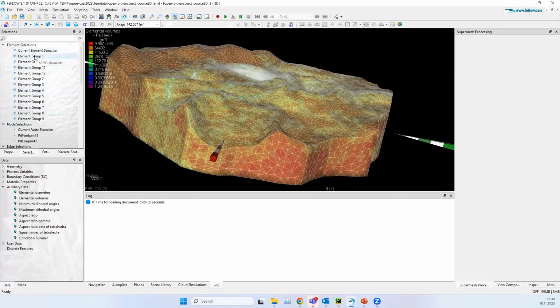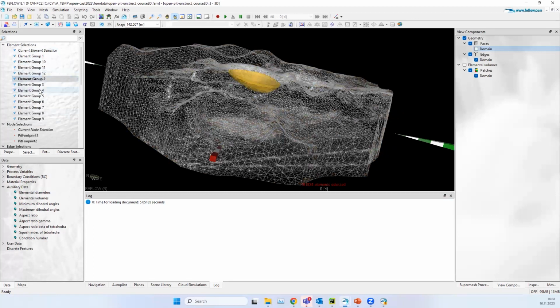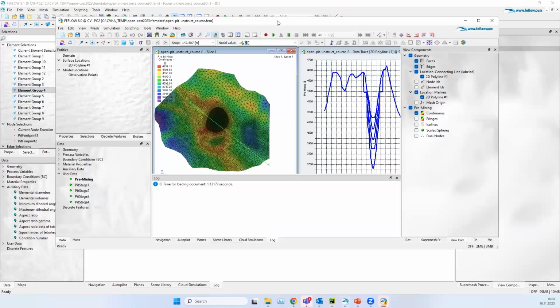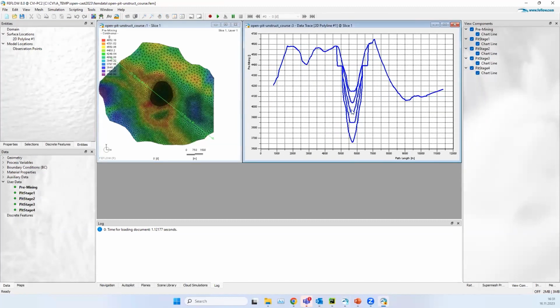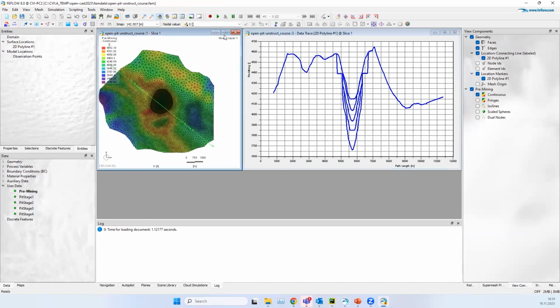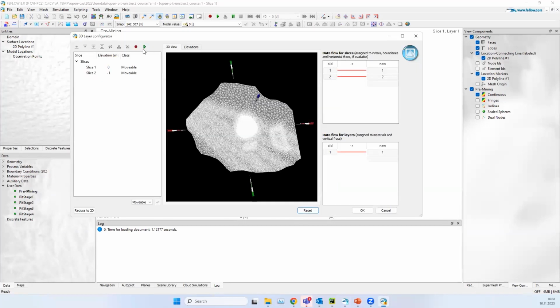The result of the 3D mesh process in FEFLOW basically creates a block of elemental selections following the shape of the different slices of surface. So we deactivate this, and I have some topographical surfaces defined, in this case the example of the mine, which I have here. These topographical surfaces define volumes in between, and these volumes are stored as elemental selections in FEFLOW.